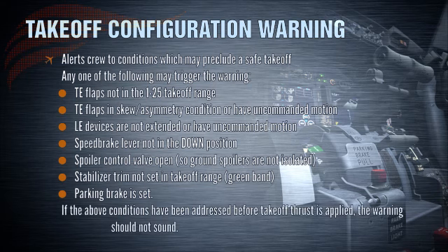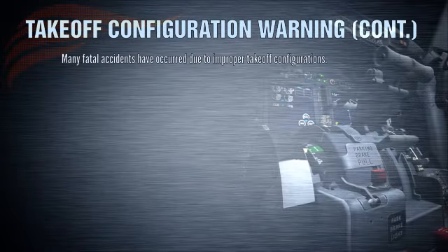If all of these conditions have been addressed by the time thrust is set for takeoff, the configuration warning should not sound. Many fatal accidents have occurred where aircraft have not been configured for takeoff, even with a configuration warning system fitted.